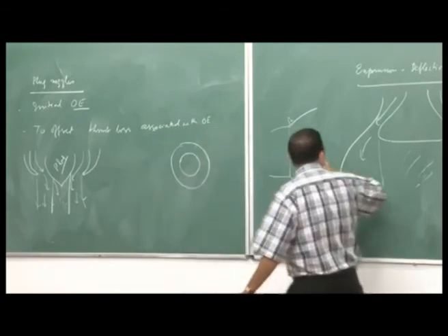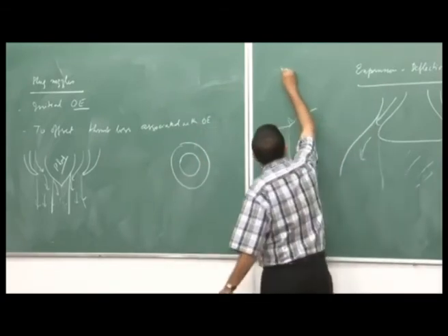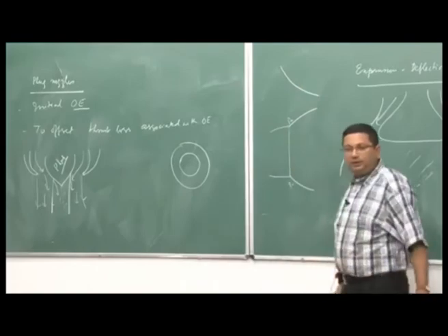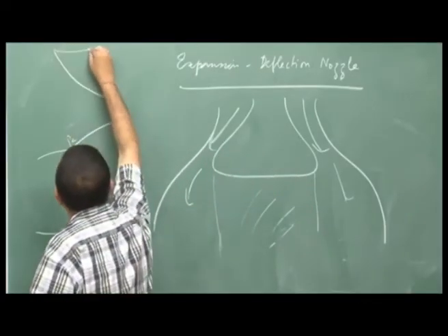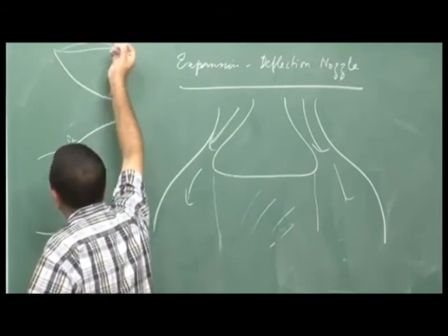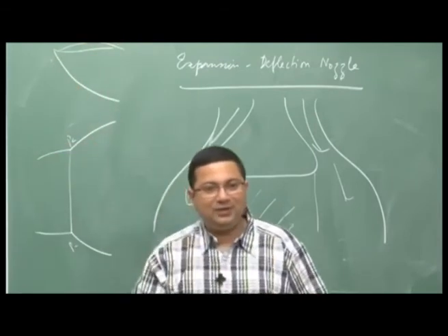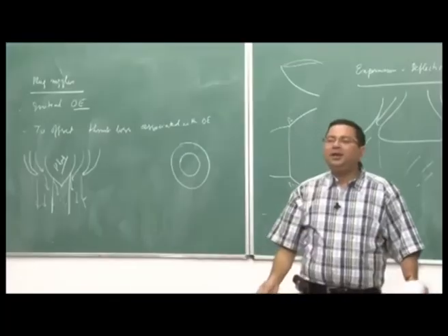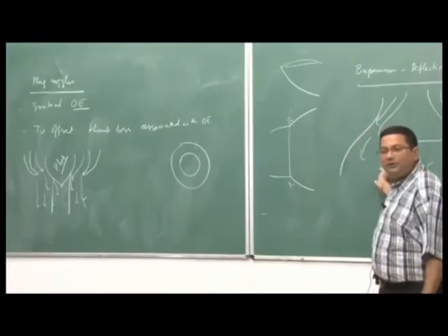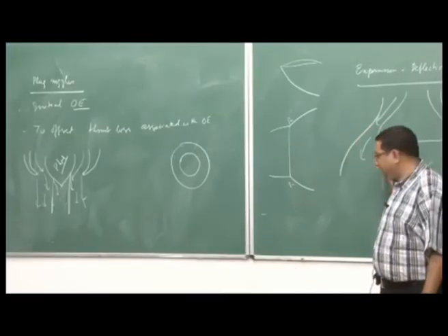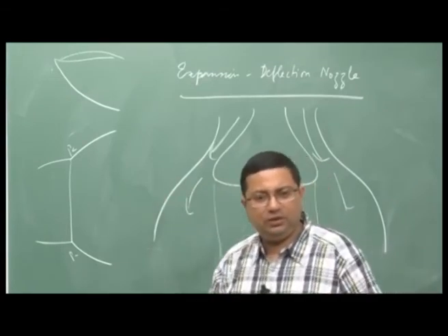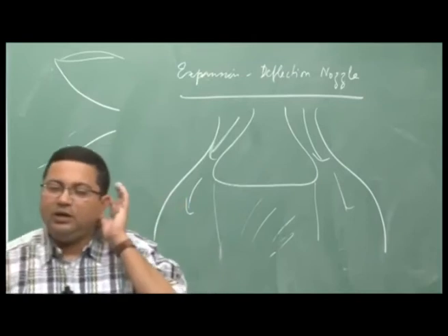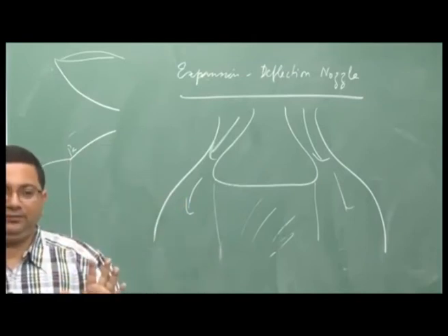So, for the over expanded case we were having a continuous drop like this. Now, that can be eliminated, we can have a uniform or an increased thrust like this. So, therefore, this is a better way of designing a nozzle rather than having a straight contour, because with a straight contour essentially you have to be very careful.